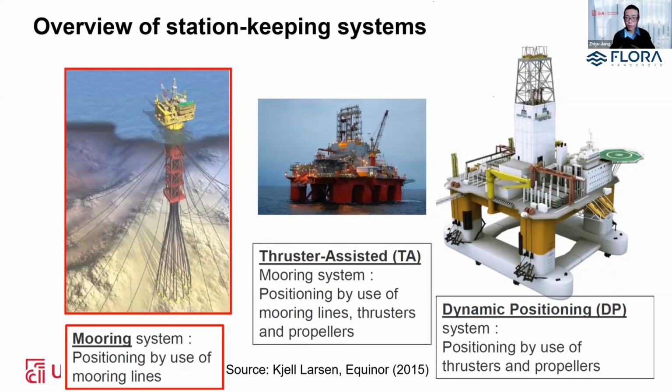Okay, this is a very common term if you browse offshore design centers. So mooring system is simply one type of the station keeping systems. Okay, this is a passive system because we do not need to rely on additional motors or burn additional diesel or fuel to keep the system in position.